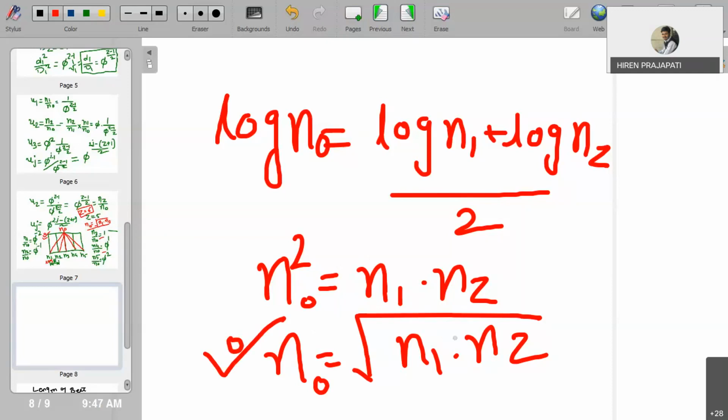So suppose your specifications of the gearbox are final, means suppose you know the range ratio, right? If you know the range ratio, which is nz to n1, this is our first step. Whenever we start the design of a gearbox, we need to first of all select the range ratio. So if the range ratio is final, if the nz and n1 values are final, then what should be the speed of the motor shaft, or what should be the input speed of the gearbox? That we can find out from this relation.